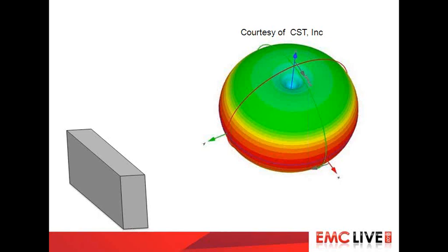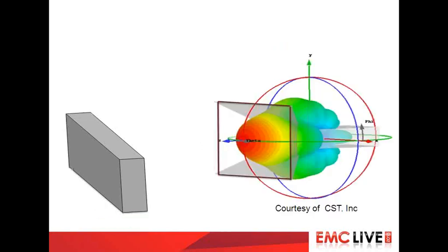However, nowadays, with much more directive antennas, I think you can see here, and again, this is that rudimentary horn antenna, that I haven't angled this very well. If that hits at 90 degrees, if that impinges at normal, much of that power will be reflected straight back at that antenna, will be captured by the antenna aperture there, and end up in the amplifier. We'll see a lot of the power it puts forward.